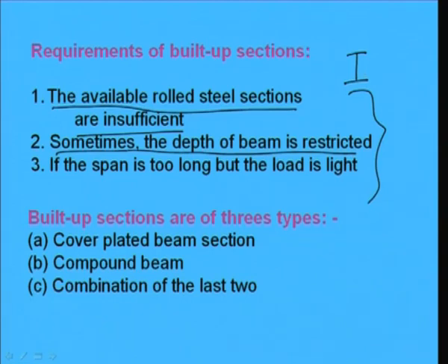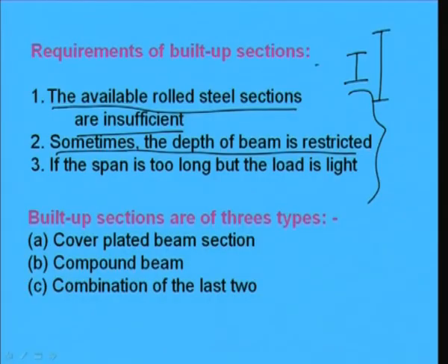So, if we use a higher I section or some other section, that may exceed the limiting depth of the beam due to certain architectural or other purpose restrictions. So, in that case we may have to go for a built up section, that means a section with lesser depth with some additional plate.